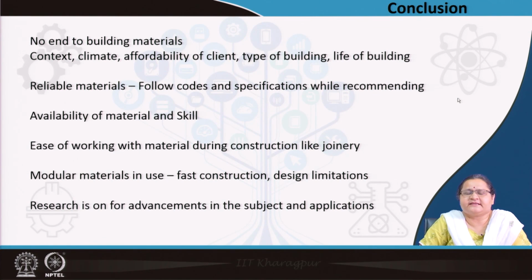So, context, climate, affordability of the client, what is the type of building, what is the expected life of the building, what is the purpose of the building, who are the users, who will maintain it, all you have to keep in mind when you are choosing or recommending a material.